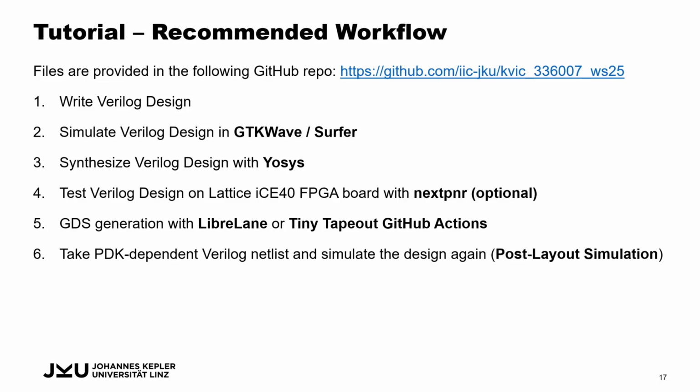Then optionally, you should test your Verilog design on a Lattice FPGA board with nextpnr. And when these steps are verified and everything is still working, then you can generate your GDS with LibreLane. Or what is also quite nice, there are templates for Tiny Tapeout on GitHub for IHP and Sky and for Verilog.